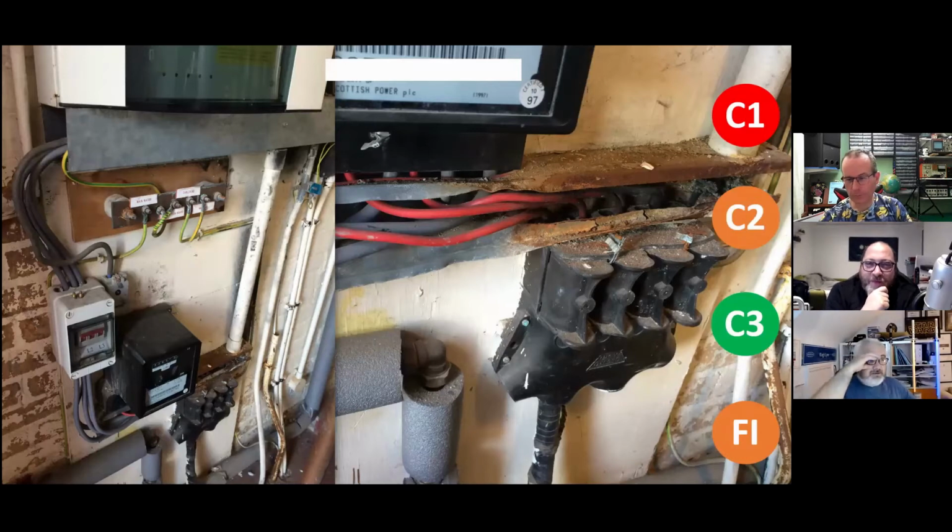Right, here's a good one. So this is a picture sent to me. This is Scottish Power. Now, this is just a catalogue of improvements, but again, it's that nasty black phenolic type cutout. Yep. Lots of corrosion, lots of rust, probably coming from water seeping through cracks in the wall. You've got obviously, the lidding's missing. You can see there's a separate earth there.